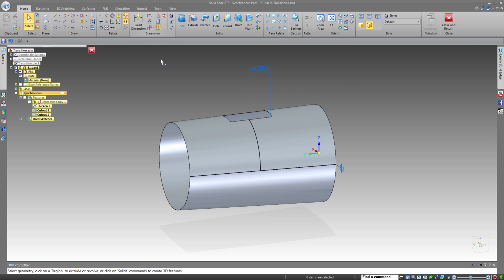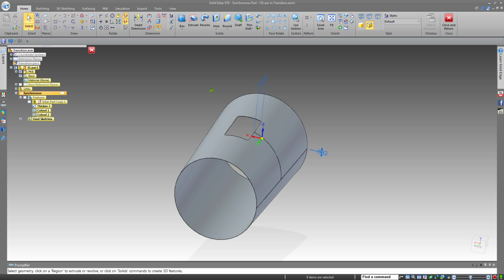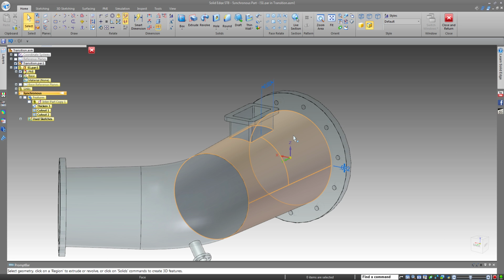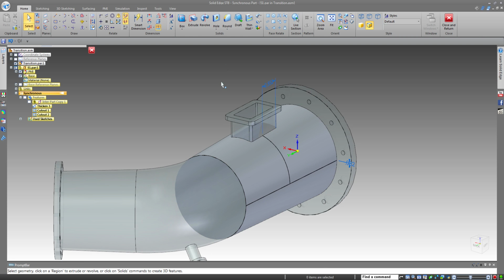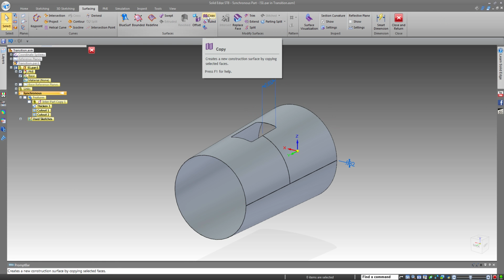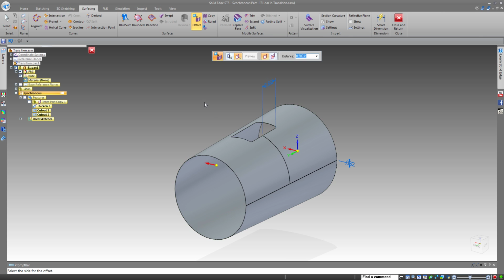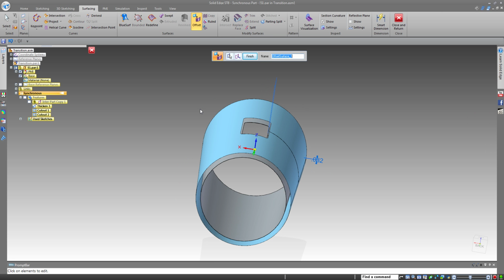All right. So if you wanted to, like I said, I want to create these into sections. So while we're here, instead of closing back to the assembly, we're just going to create some multi-body parts. We're going to basically create the outside surface off of this, and then we'll create all the intermediate pieces. All right, so let's go ahead and take care of that. So surfacing, we know we want a 1/2 inch offset on this jacket, so I'm going to say offset from the outside edge, again to the outside.